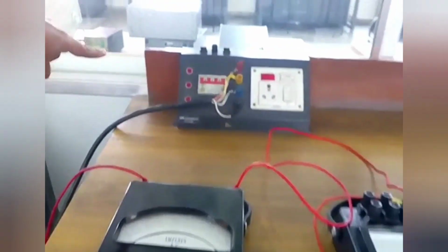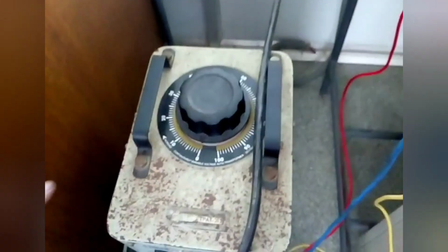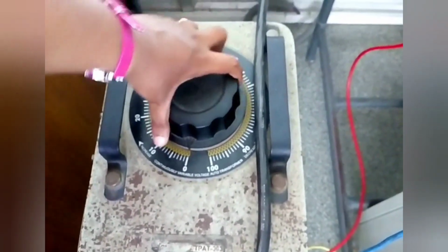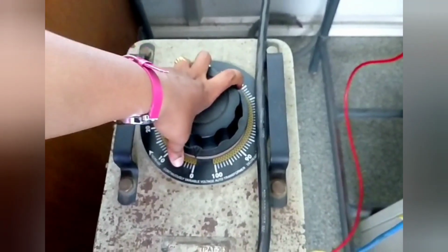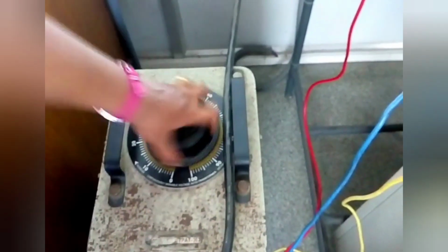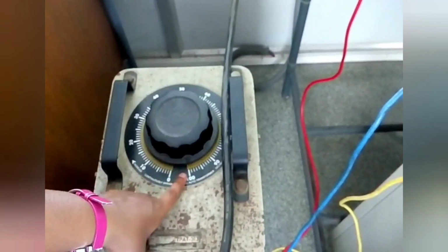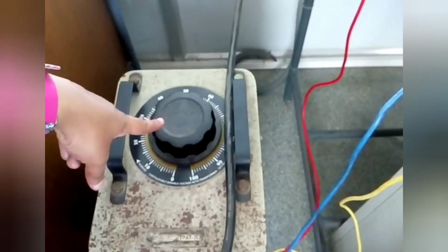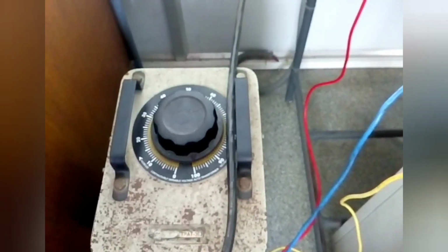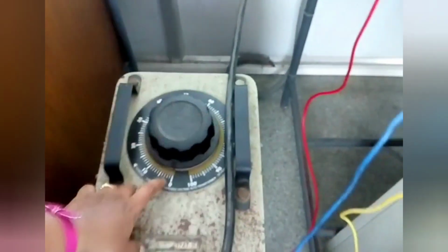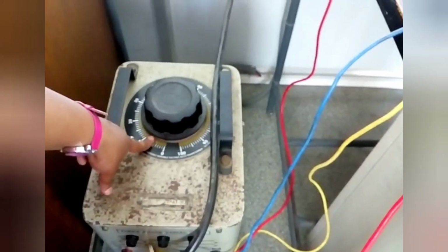TPST switch is in off position. Okay. So the auto transformer should be in minimum position. This is one of the major precautions. Always observe this auto transformer. This variac should be in zero position, because if you don't check this, maybe it will be in the maximum position like this, at 400 volts, and if you immediately switch on, if there is any wrong connection, we are getting directly 400 volt supply from the auto transformer. So never do that. Always don't forget to check that the auto transformer should be in the minimum position like this.